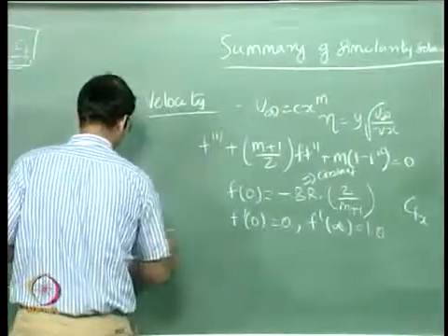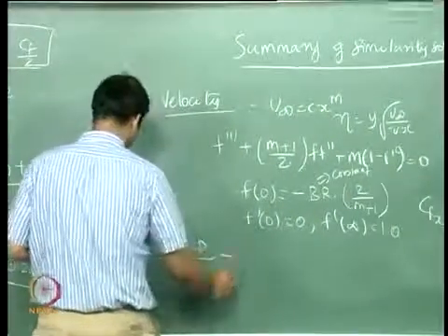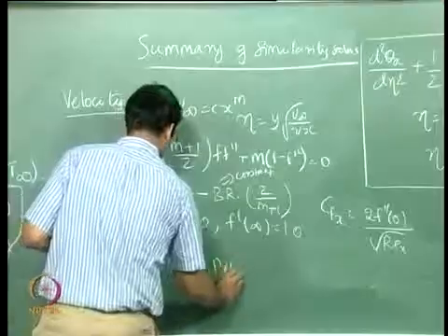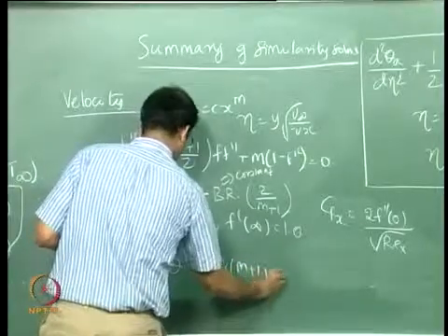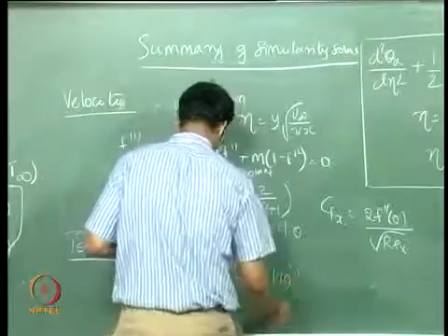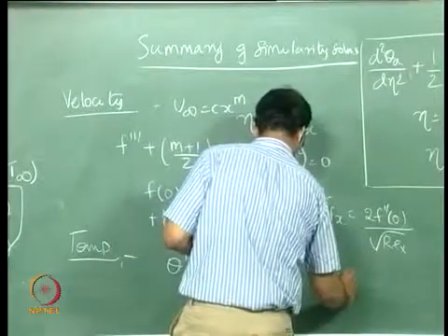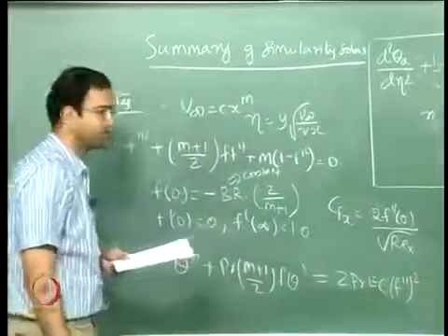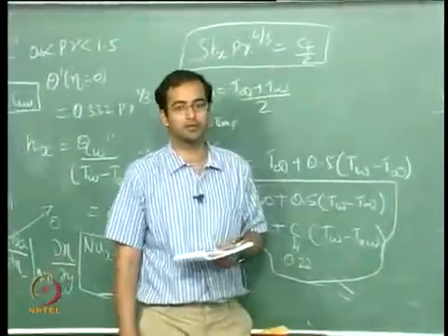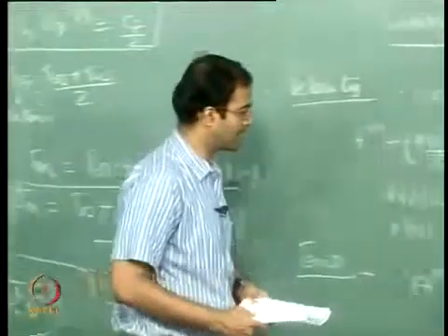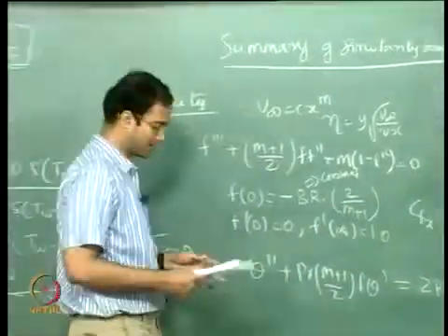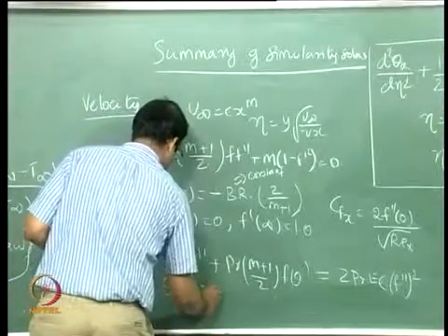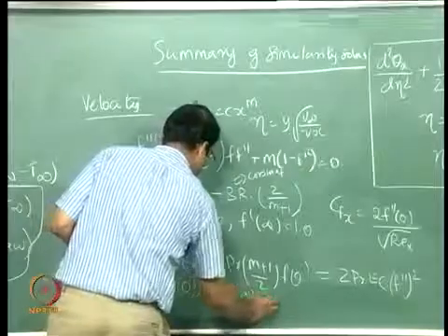In the same way for temperature, the most general similarity solution is theta... this is your most general form, including high speed flows. Okay, if your Eckert number is small, you can neglect the right hand side terms and it reduces to Pohlhausen's equation. The boundary conditions are theta 0 equal to 1, theta at infinity equal to...